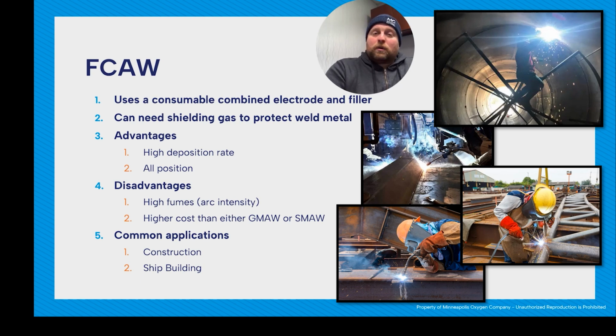I believe worldwide, flux core, at least cored wire, is used more than any other type of wire. So GMAW, I think, probably would be your most used process. Flux core puts down more wire in a year than probably anything else. It's great for big joints, great for construction things, all sorts of stuff like that. So advantages, a high deposition rate. We're putting down a ton of metal fast. That's what deposition is. And then you can use it in all positions.